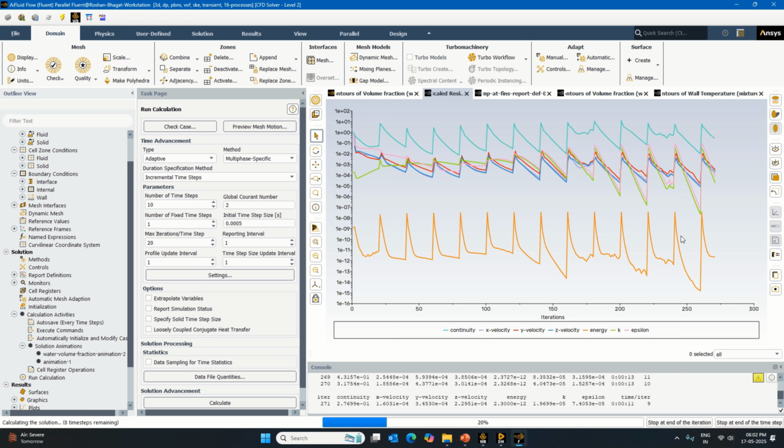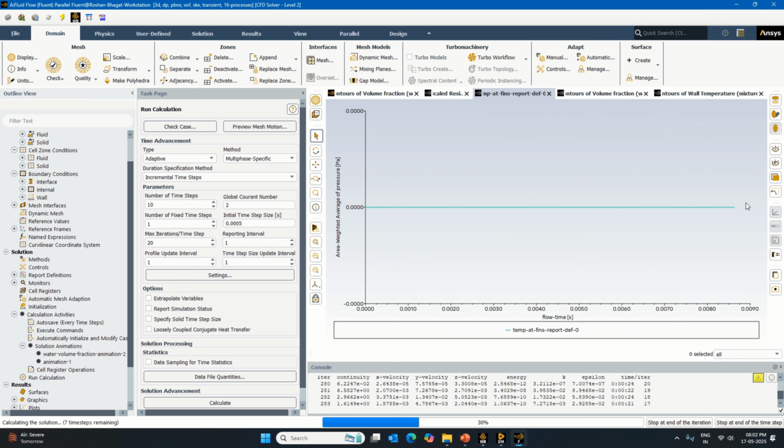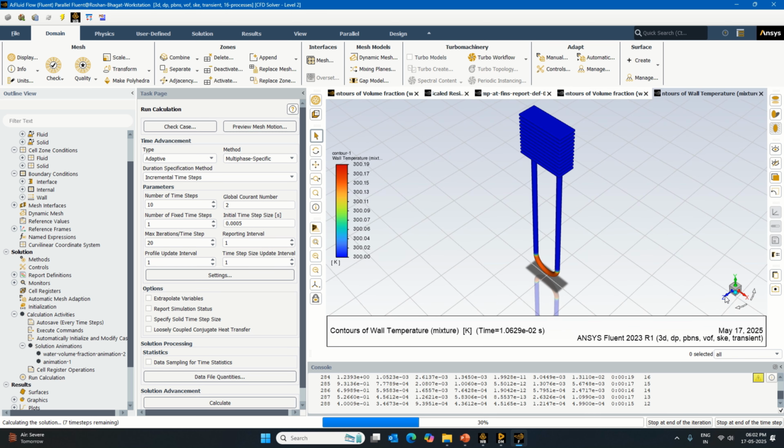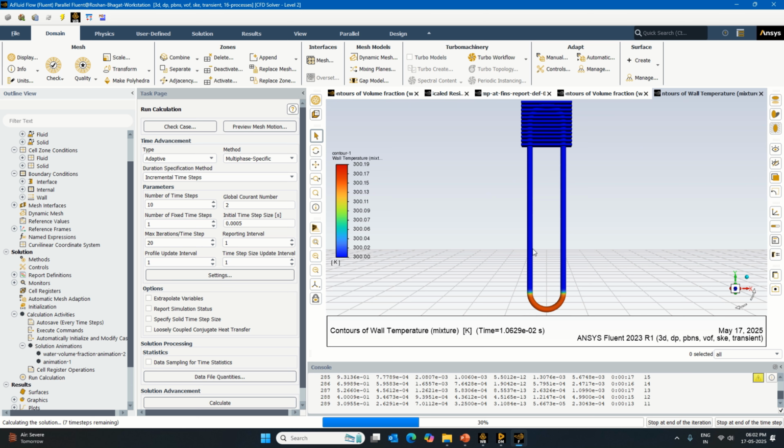Whenever we observe the floating point exception error, there are chances that the lower one and the upper one are intersecting with respect to each other, and you can predict when the floating point exception error can occur. So this is one way of predicting things. We did it slightly on the wrong side, so you can modify it. And here you can see the temperature distribution.